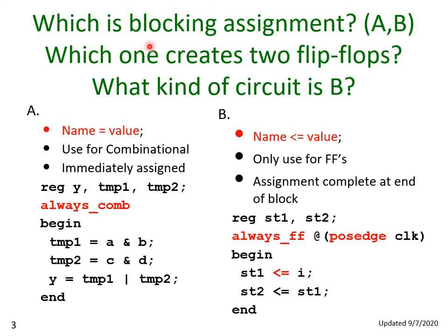So having said that, which of these pieces of code do you think create flip-flops? Well, hopefully I've said enough here that would give you some clues. One, the notes right here say that this is combinational logic. Flip-flop is a kind of sequential logic. It's not combinational. So that alone would tell you. Conversely, over here, we have a clock edge sensitive function, and a value gets assigned to the output on a clock edge, which is a way of describing the behavior of a flip-flop. So we've got a variety of evidence that these are flip-flops.